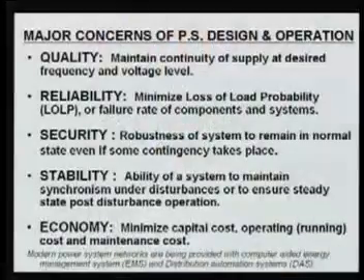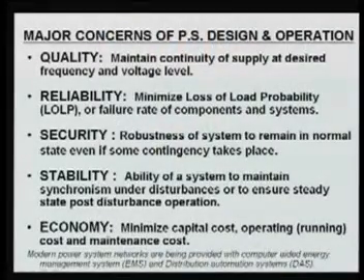Reliability of a power system is related to minimizing the loss of load probability, that is called LOLP, or the failure rate of components and the system. We have to design our power system so that the elements have the least probability of failure, meaning minimum equipment damage or equipment failure in the system.